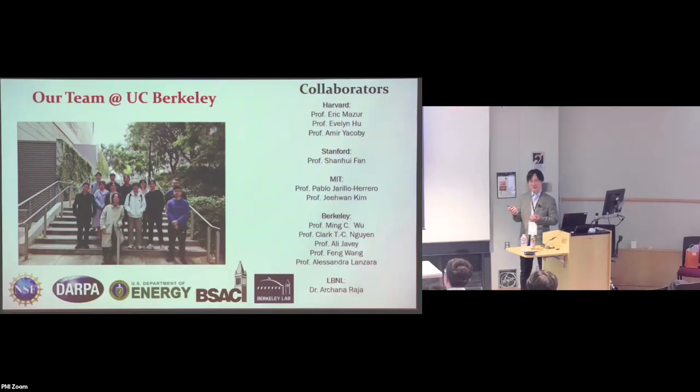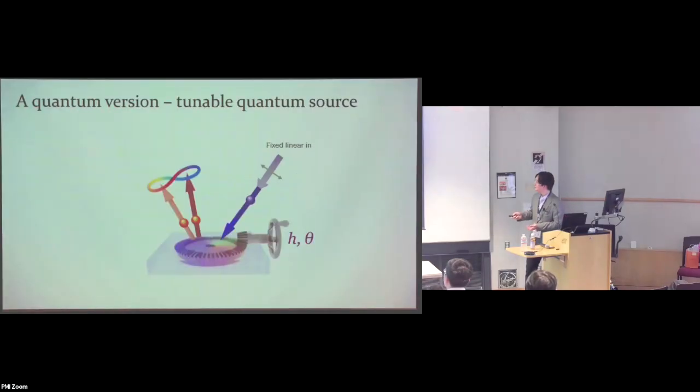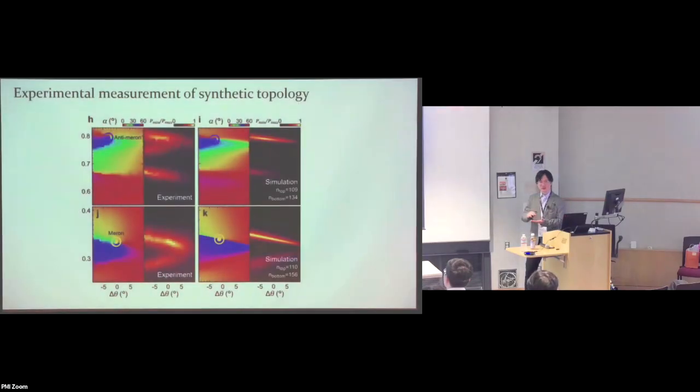Yeah, so there's no limitation on gating, right? We can use the tip for gating for one thing, and you can put whatever bottom gate. That doesn't really affect the operation of this device. In terms of the layers, you basically have one device where you can control one interface, right? So you can distribute how many layers you put on the pyramid and how many layers you put on the substrate. As long as you're only twisting one of the interfaces, then you can use this device.